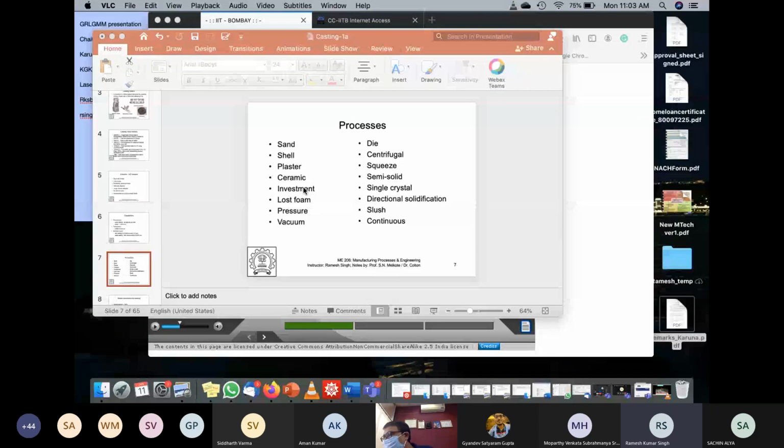It can be hollow in shell casting if you have what? If you have a core there. So you have to leave the core there to create the hollow pattern. Otherwise, you will get a solid thing. The product is not the shell. The casting mold is a shell.